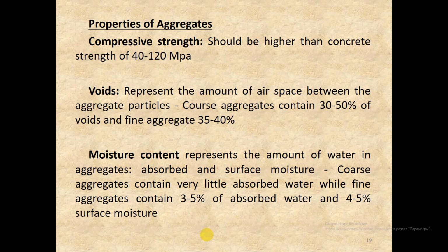With coarse aggregate, the material should be inspected visually and a knife used to scrape individual particles to ensure clay is not adhering to the aggregate. Coarse aggregate should be inspected to ensure it has not been placed in layers on the truck. All aggregates should be well mixed before loading. Layered loads should be discarded.